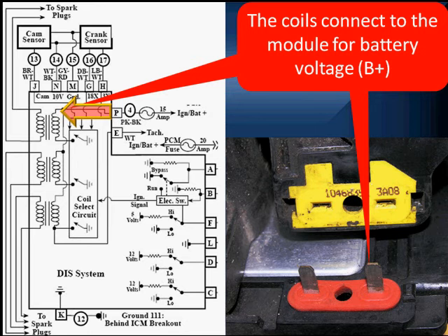Notice that this wiring connects directly to 3 separate primaries. This is a 6-cylinder engine, so what it has is 3 primaries, each primary firing a series of spark plugs. So when we look at this one signal up on the pink wire, pin P, we're going to be measuring current for all 3 coils. Now, this is something we do without thinking about it very much when we're talking about DIS. We frequently forget doing that.